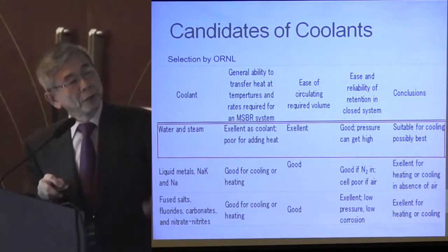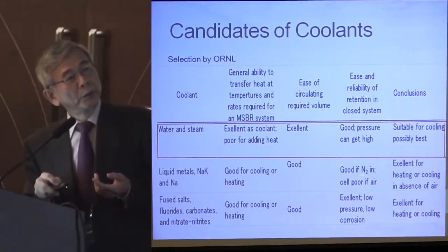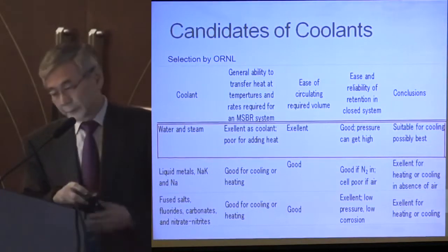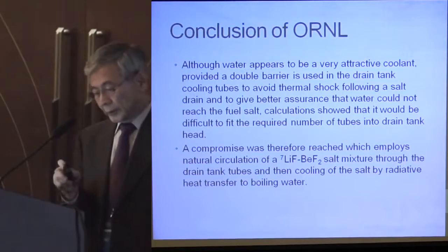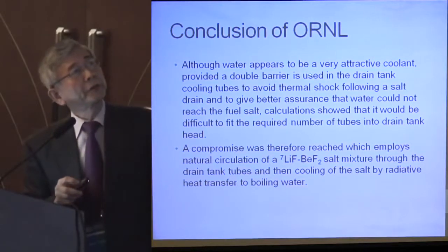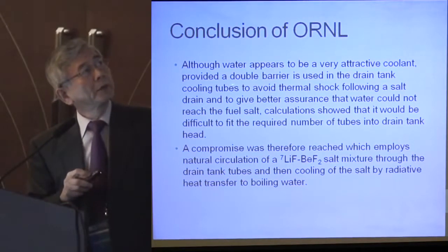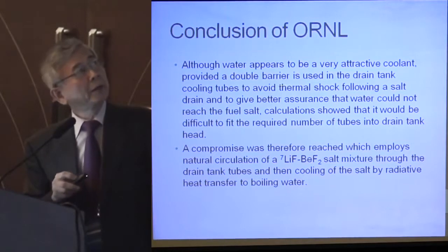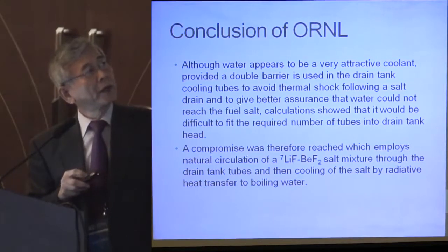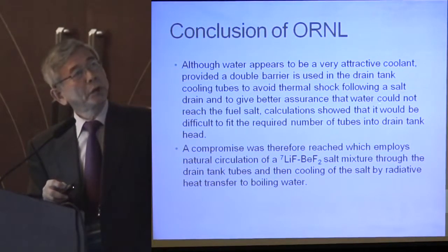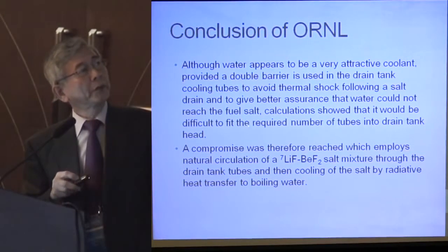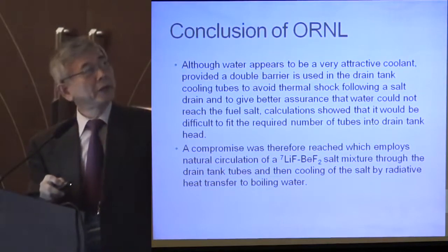This must be filled with a nitrogen atmosphere and something like this. And I quote the conclusion of ORNL. It says, although water appears to be a fairly attractive coolant, provided a double barrier is used in the drain tank cooling tubes to avoid thermal shock following a salt drain, and to give better assurance that water could not reach the fuel salt, calculations showed that it would be difficult to fit the required number of tubes into the drain tank head.